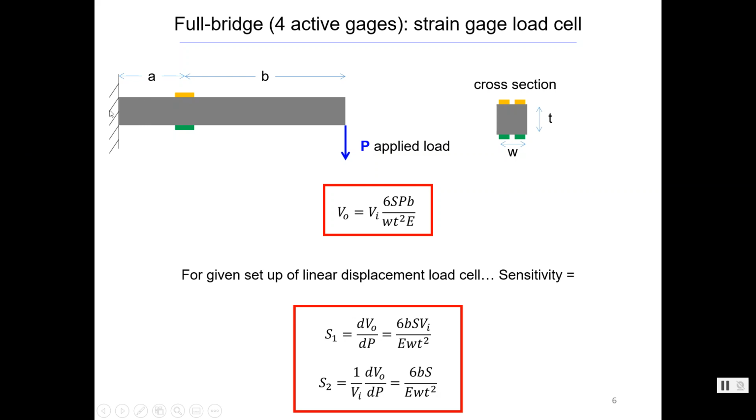So we have that load cell apparatus, and we apply loads on the end. And what we would do is we would take this load cell, we would set it up in one of the ways that I just described, and we'd write a simple VI in LabVIEW so that we collect that output voltage.